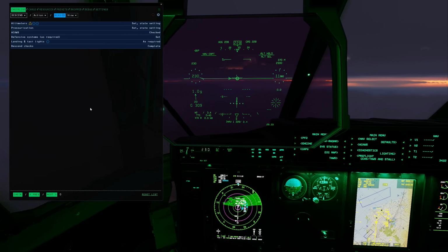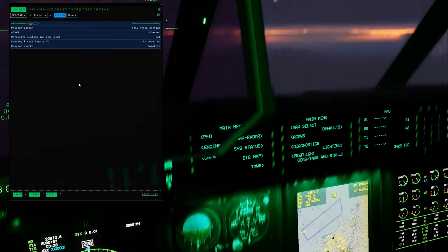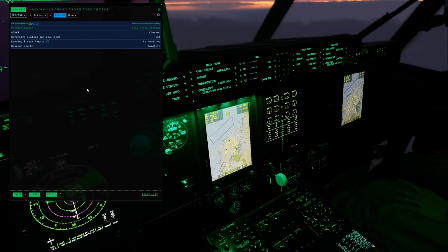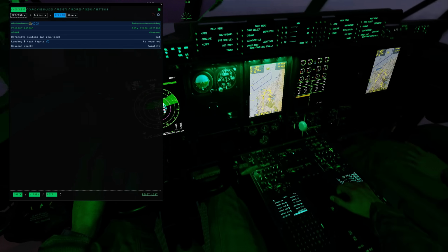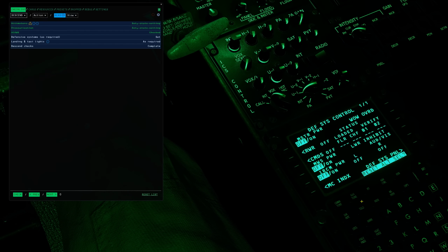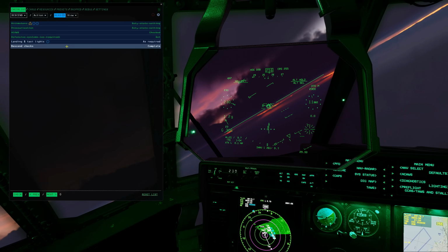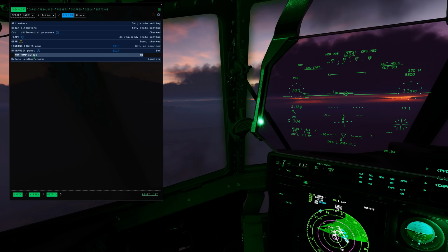Ready. Altimeter? Altimeter barometric set 29.33. Pressurization? Cabin altitude is 3,000. ACAWS? ACAWS clear. I have no messages. Checked. Defensive systems, I got that one. Okay. Clearing the master caution. Okay, defensive system checked. Landing and taxi lights. Set. And the descent checklist is complete. Okay. Go ahead and set it for before landing, so we got that ready.